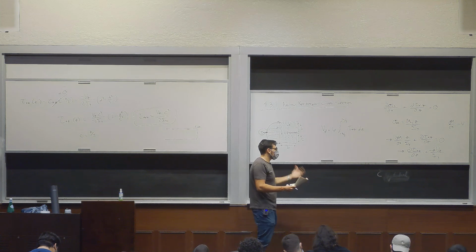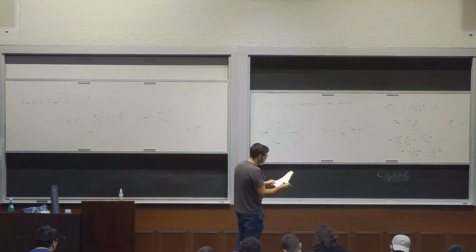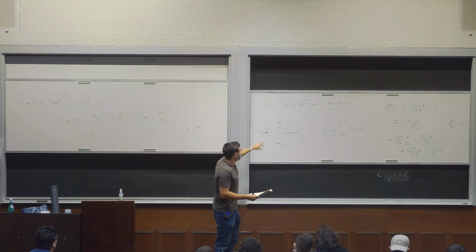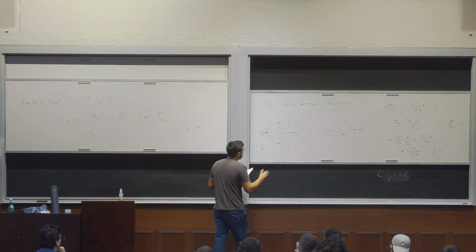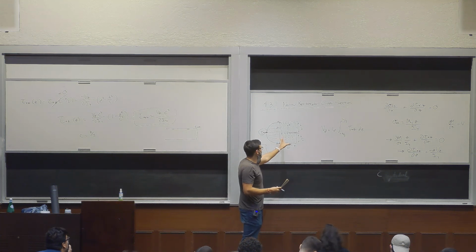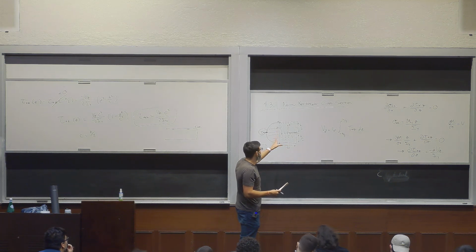That's often too complicated to solve for. So what we solve for in those problems, rather than tau, is q. Remember the shear flow? We solve for q in any cross section where the dimension y might not be constant, or it's large enough for there to be some variance.